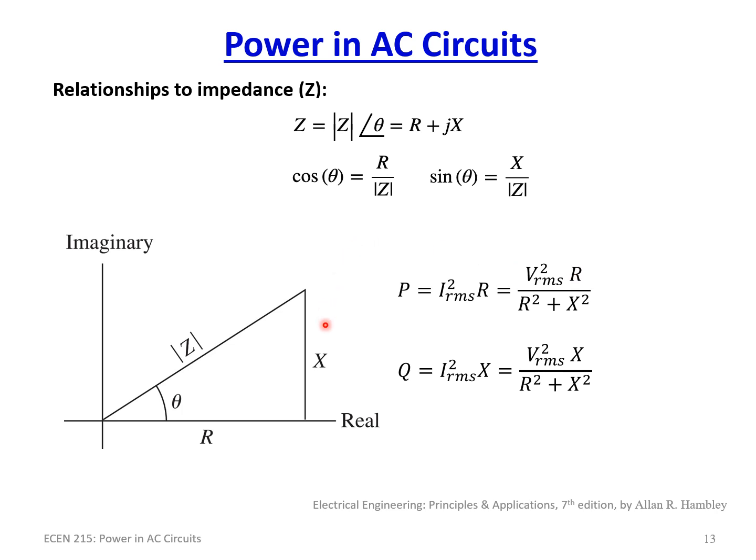So here, if you're given an impedance and you're asked what is the power, and you only have one of the values like IRMS or VRMS, now you're able to solve using your I squared R and V squared over R, or in this case Z type equations.